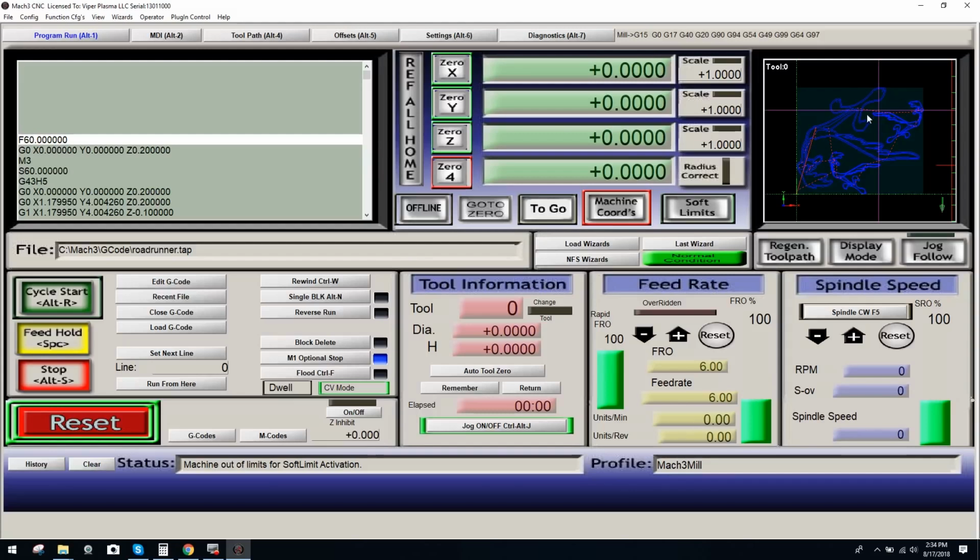You also saw that the representation of the gantry has now shifted all the way over up towards the top right of the actual toolpath box, and that's just a direct representation right now. Mainly it's off because we have not regenerated our toolpath. We'll do that in a second.